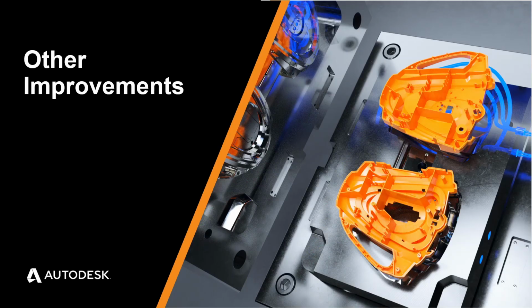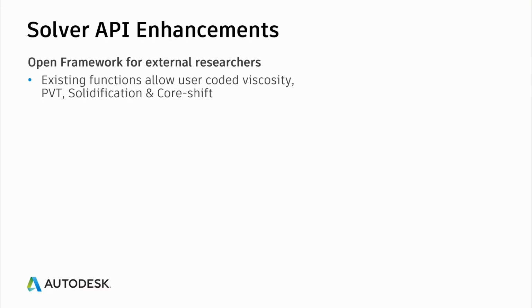Next, we'll look at some other improvements that we are hoping to deliver in the forthcoming commercial release. The first of these concerns the Solver API enhancements which have been made. I'll remind you that the Solver API is an open framework for external researchers to enhance the calculations being done in our 3D Flow and Warp Solver. Up to date, there are existing capabilities for users to code their own viscosity, PVT, solidification, and core shift functions, which allow them to model different processes or different materials than what are normally handled by our solvers.